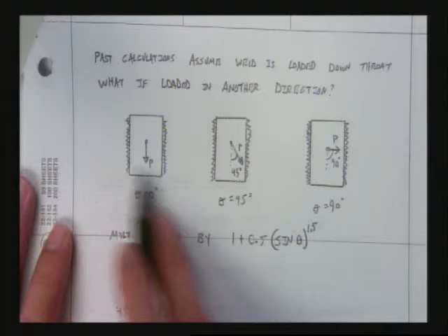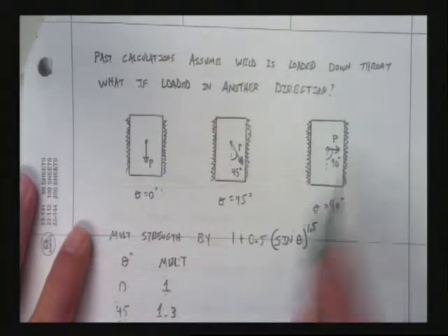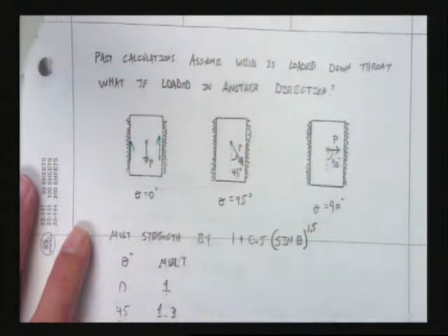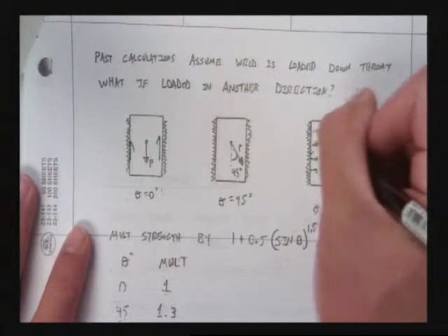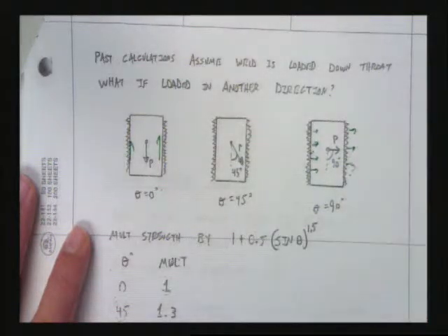But what if we have welds in tension? I'm sorry, yes, this would be a weld failing in shear, and this would be a weld failing in tension, and this would be another weld again failing in tension, right? That would have to happen for that system to fail.